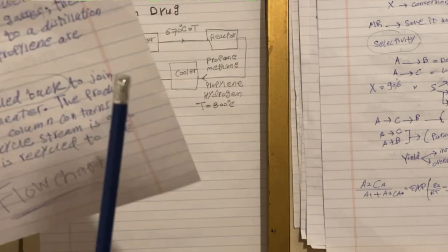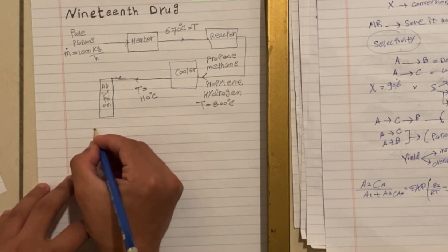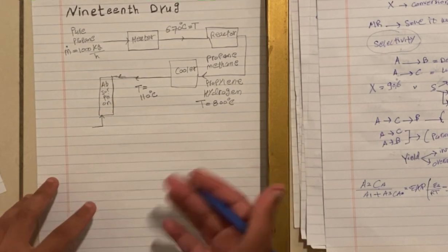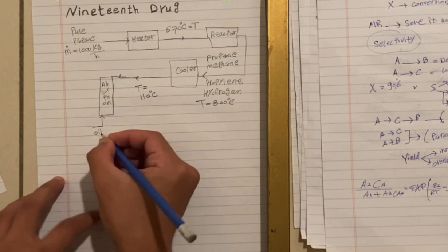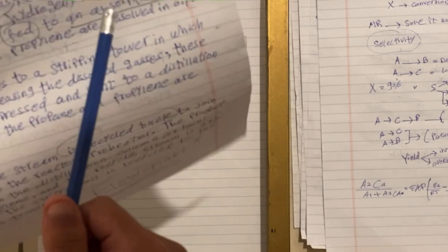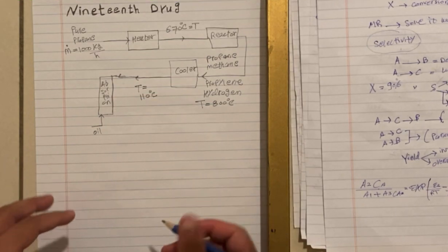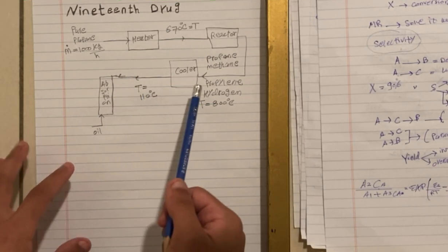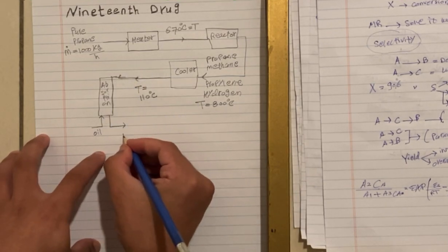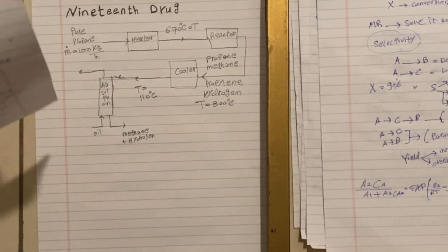These four chemicals, two of them will be dissolved in oil, which means that we will have a new stream in the absorption tower, feedstock or feed, which is oil. How can there be no oil if he said or she said that we have an oil that will take propylene and propane? It means we have an oil that will come to the absorption tower that will capture the propane and propylene. The stream that enters here will leave with methane and hydrogen only. The oil will leave, it said, will go to a stripping tower.